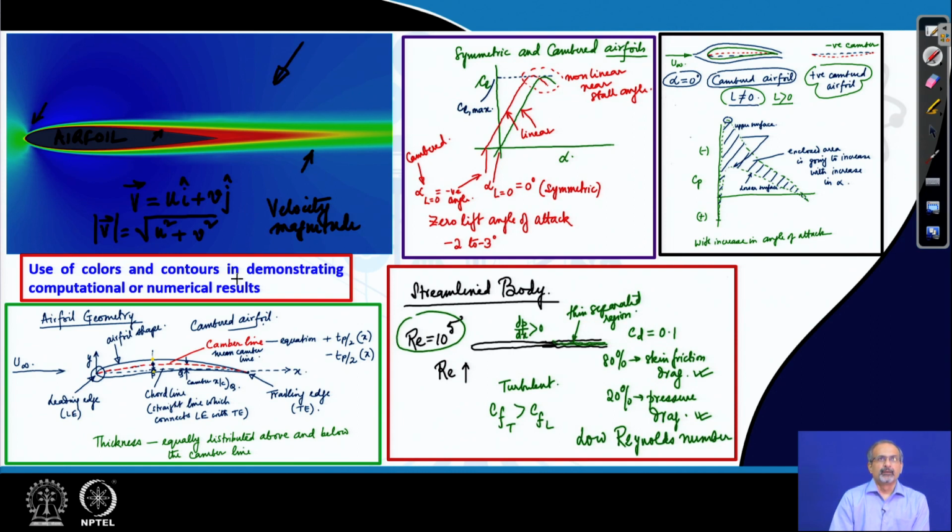Okay. So, we have learnt about airfoil geometry, for example, and then let us try to revisit what we tried learning there. So, there we said that in the xy system, we can place the leading edge of the airfoil at 0 0, and then we take a certain length along the x axis, and that would essentially give us the chord length of the airfoil. So, we often designate it by c, lowercase c, and the straight line of c length from the 0 0 point is essentially the chord line.